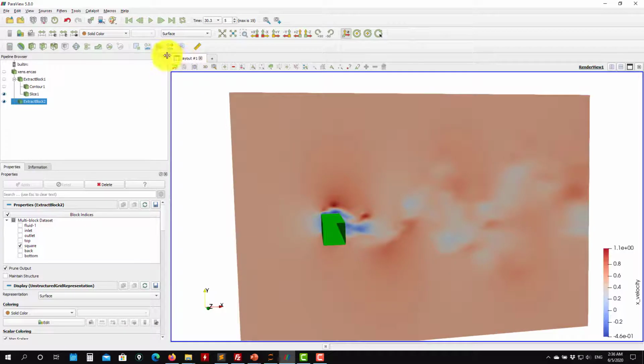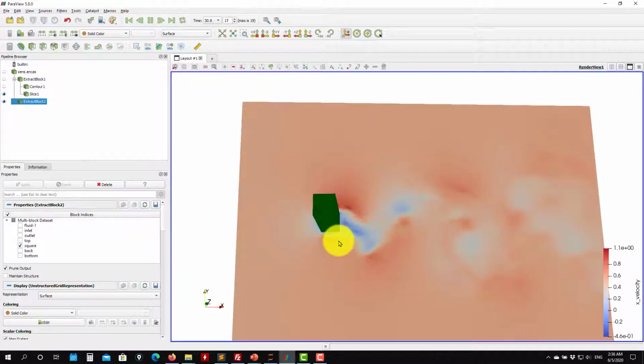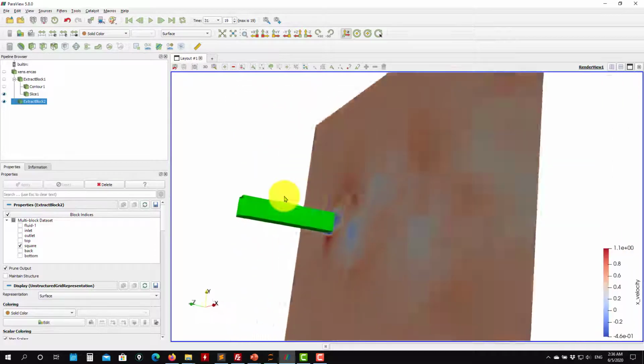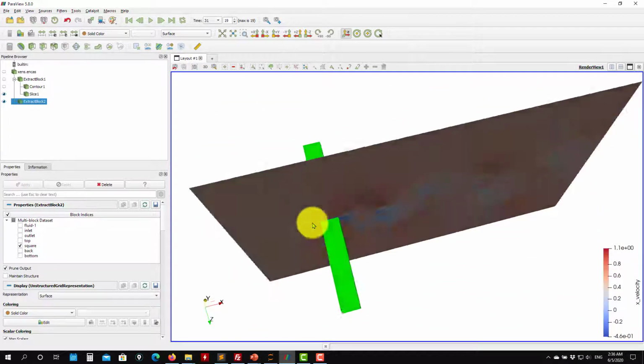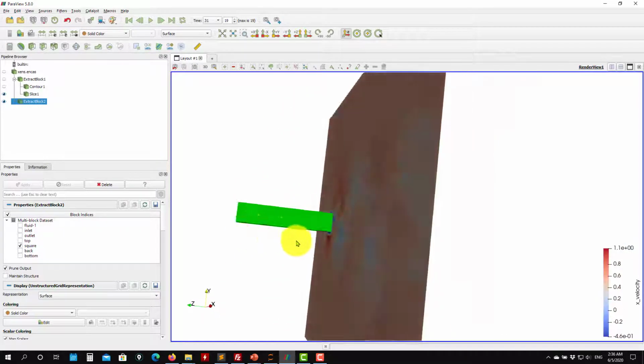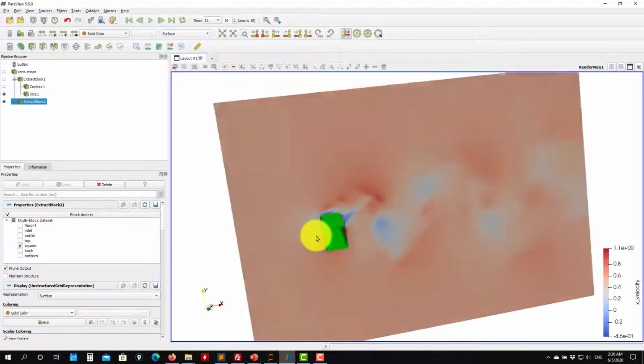And if we press play, you have there your solution. Here you have all the filters. Also, we already did it for the case of the budget, so you can do sampling in a point, in a line. Okay, you have all the options. So this kind of post-processing is very tricky to do within Fluent. So Paraview, we can use it, and it's very easy to use.